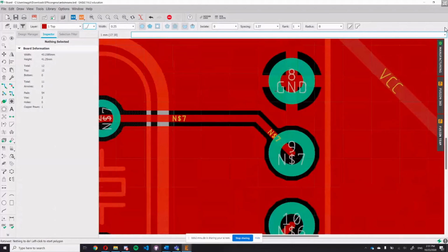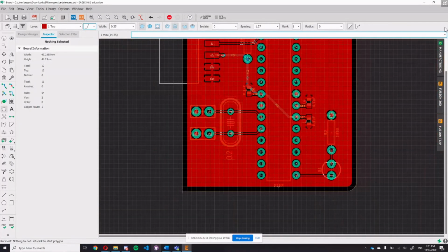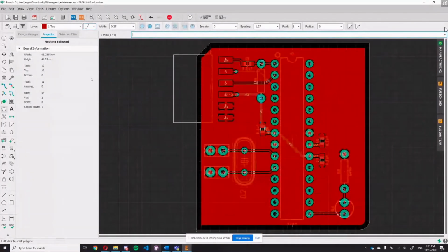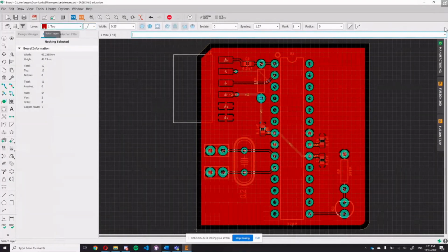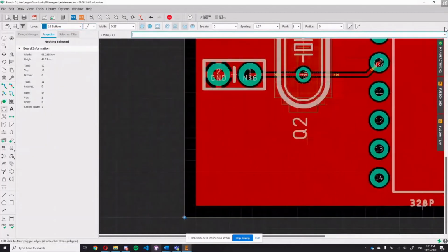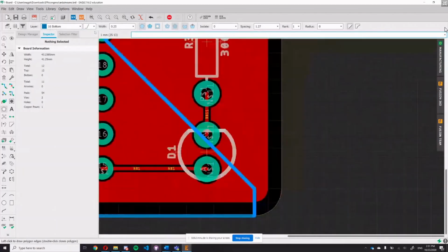And when a signal is ground, it's connected to it this way. So this is called thermal, and it basically just makes the soldering process easier. So we have this, and we just need to do that to the other side as well. So we just select bottom, and we do the same. So that shouldn't be a problem.